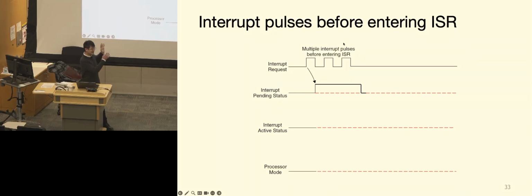So it's a cooked question for you, but it does happen in real life. This is so that we can have you look at the interrupt pending signal, the state that covers more than one rising edge of the request. The reason it takes longer is because the processor is taking longer to actually enter the handler mode.